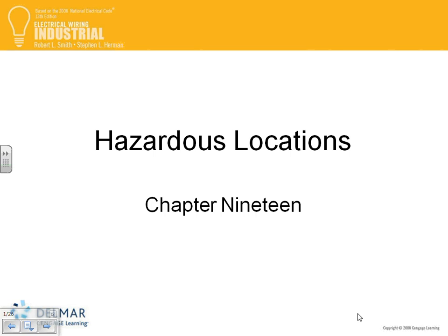Divisions, Eric, my friend, you can listen to your friend Chad one more time. Divisions are: Division 1, the hazard exists all the time. Division 2, the hazard will exist under abnormal condition, malfunction of equipment. That's it. And sometimes, Brad, the area adjacent to class 1 in a lot of places, they call it also class 2. So if class 1 flammable gas is here, the area directly adjacent to class 1, they classify it as a class 2 because it could have the hazard.